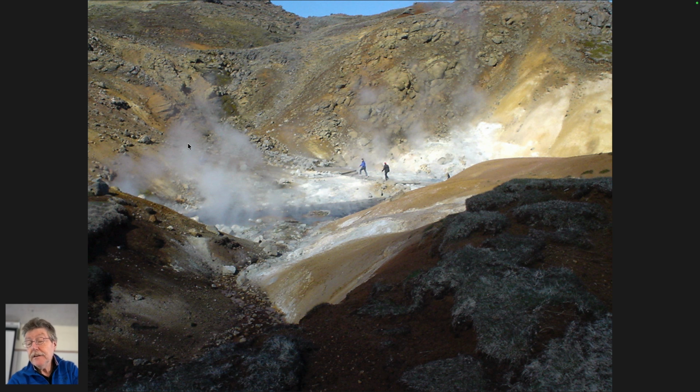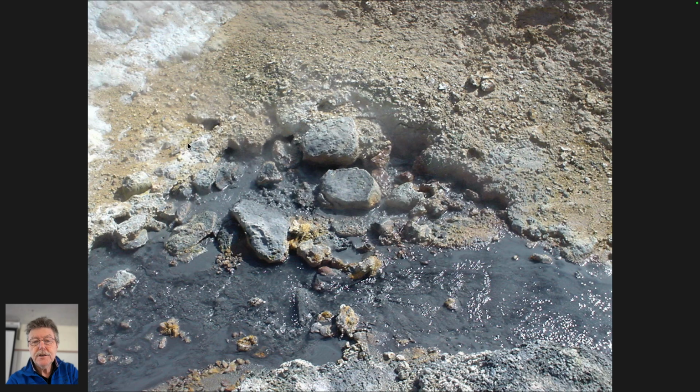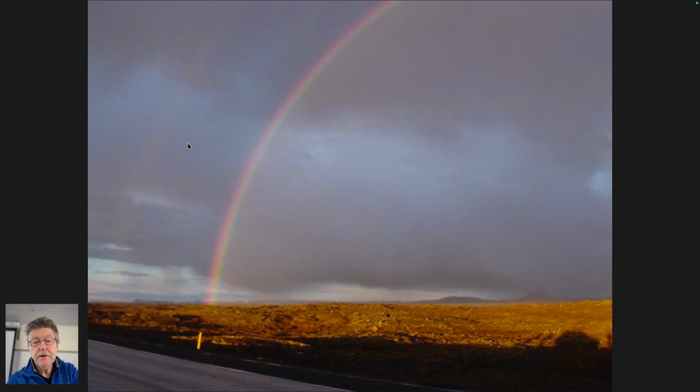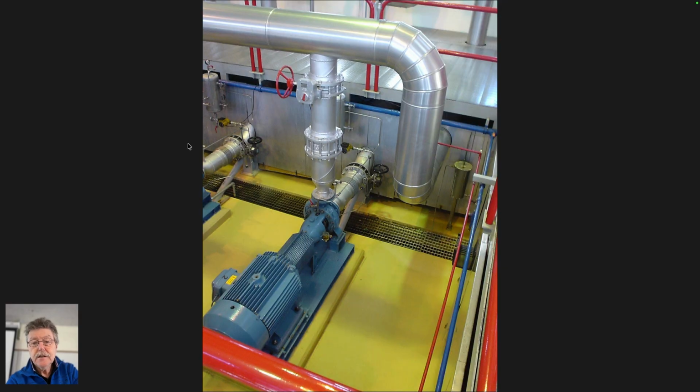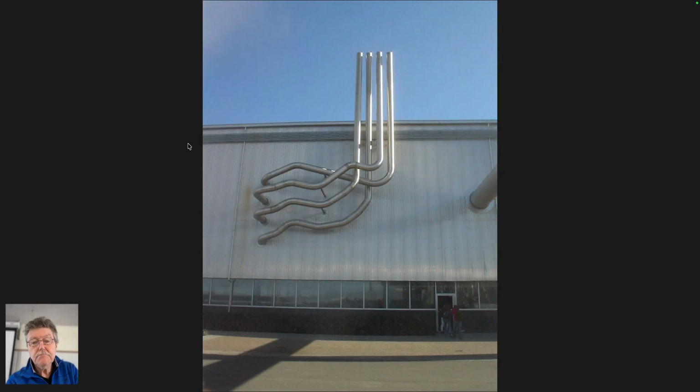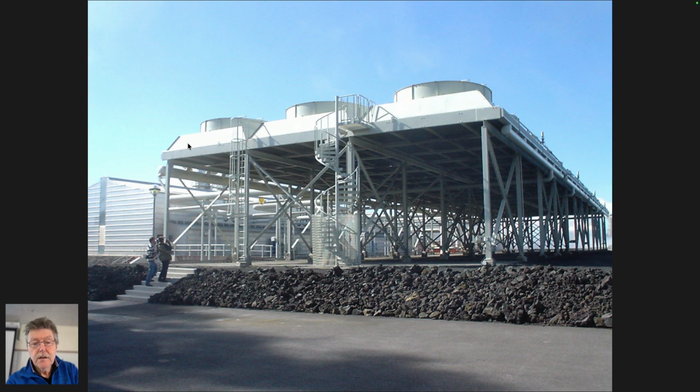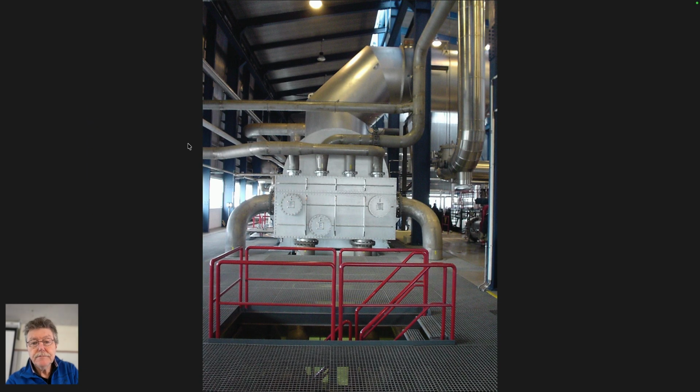Obviously, if you're prospecting for this, you don't have to be too clever because you can recognize that you have high heat flow and abundant fluid flow at shallow depths. Perfect location for a geothermal plant, very pretty. Again, a very clean plant, pulling water into a turbine hole. The pipes are relatively small diameter, maybe 6 inches inside sheathing, which is perhaps 18 inches in diameter to keep temperatures. Very picturesque. You know what those are, condensers.